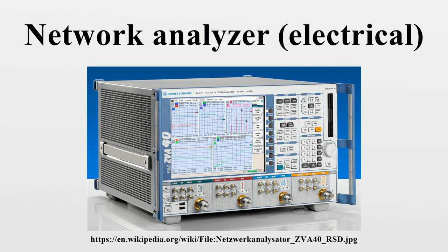The simplest SNA will have a single test port, but more accurate measurements are made when a reference port is also used. The reference port will compensate for amplitude variations in the test signal at the measurement plane. It is possible to share a single detector and use it for both the reference port and the test port by making two measurement passes.